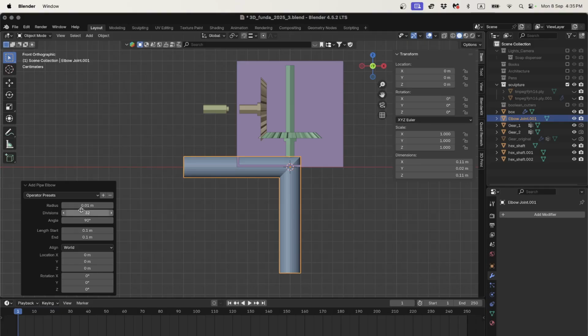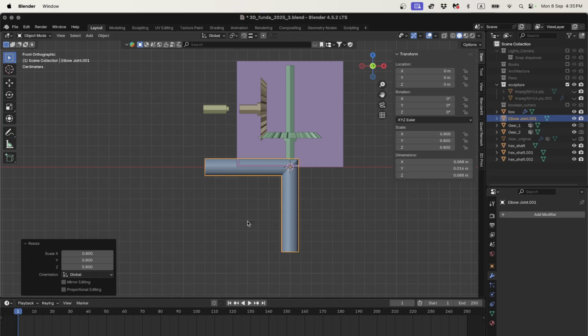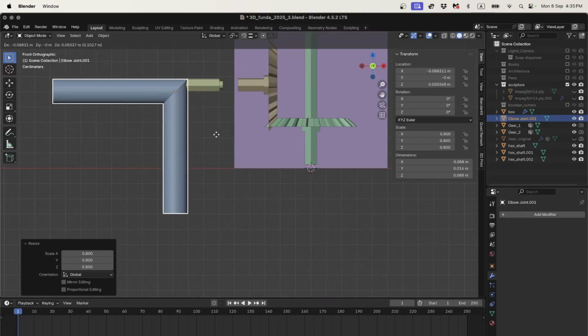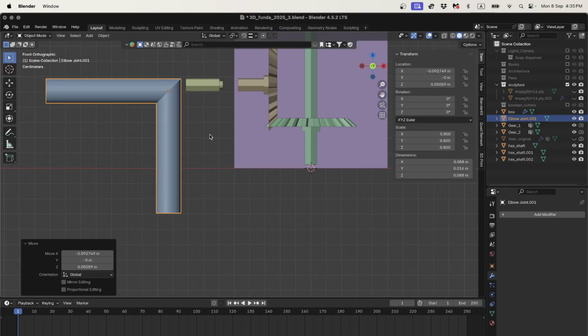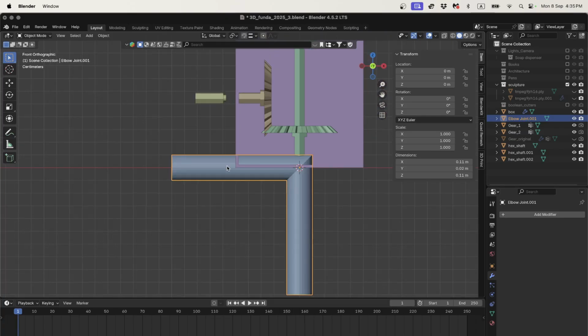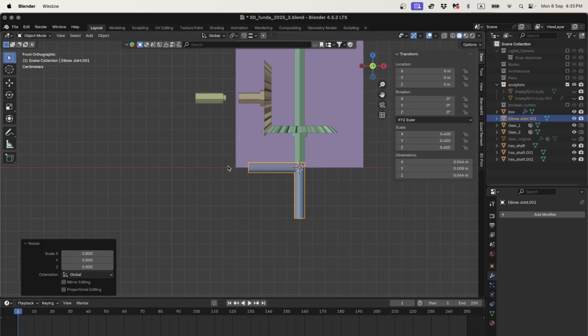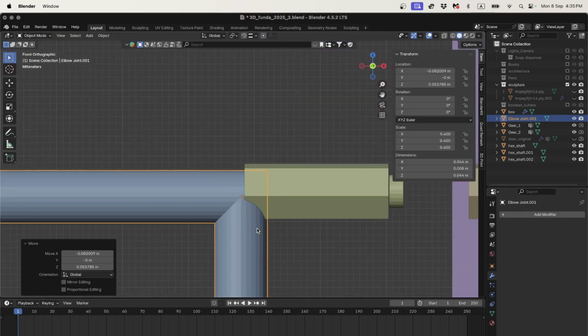Okay, even though I put in 0.004, it's gone to 0.01. That means it has a minimum radius of 1 centimeter, but that's easy to scale. From 1 centimeter to 8mm would just be S .8. Now that, to my mind, should be... nope, I've done something wrong here. S .5, S .8. Okay, I think I was twice too big.